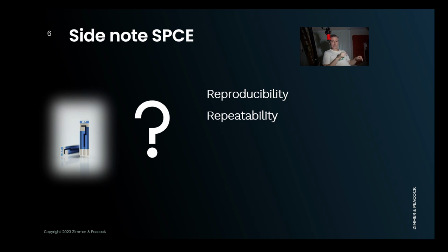Irreproducibility in the manufacturing of these screen printed electrodes, and even if you make them in-house, I think there's often an even worse situation, where you don't get reproducibility. It then leads you to terrible repeatability in the lab. Or terrible is overstating it. But sometimes you'll have to do 5 tests in order to get 3 tests that make sense, because you think that 2 of the tests are outliers, and you have a strong suspicion those 2 outliers are actually down to the screen printed carbon electrodes.